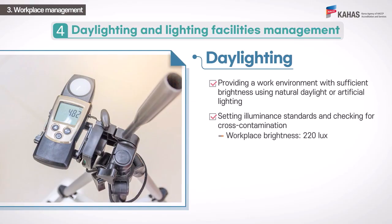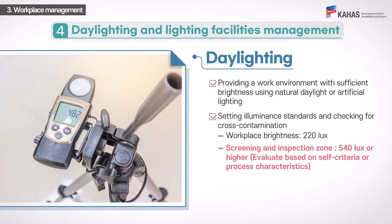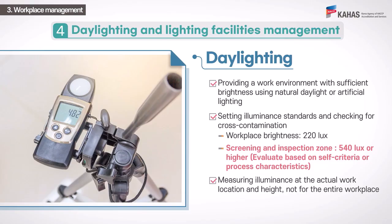The brightness of the workplace shall be 220 lux, and the screening and inspection zone shall be 540 lux or higher, etc. The illuminance of the workplace is measured at the actual work location and height, not for the entire workplace.